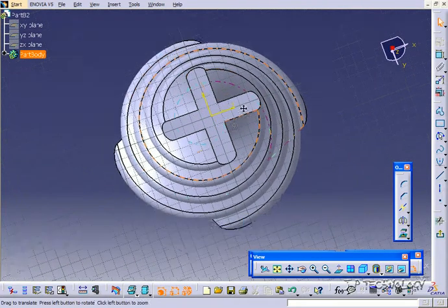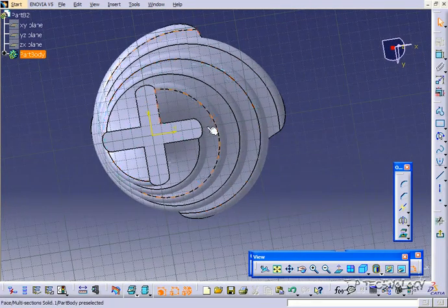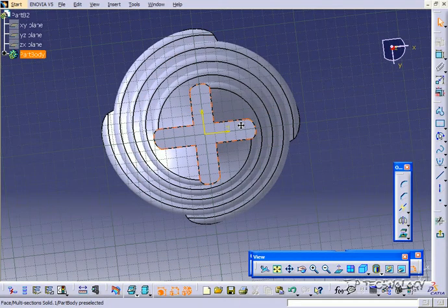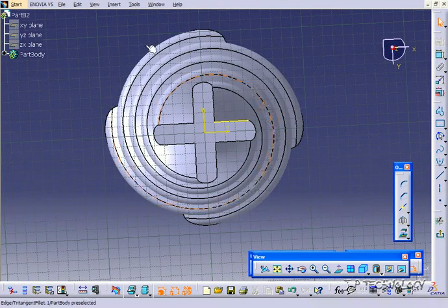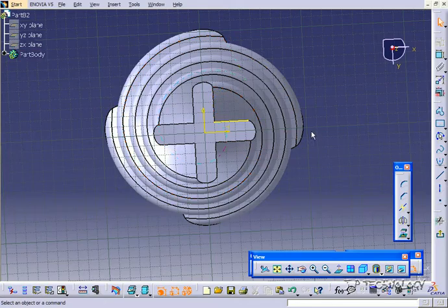And again, like I said, this is probably the most important tool, I think, in sketching in CATIA, because you're going to have to project those edges, and it's going to allow you to make precise drawings and make features off of those features there. So to start off, to use this tool, all you have to do is click Project, click a line, and now you've projected a line. Whenever you project them, they're going to be yellow unless you've changed it in your tools and options.